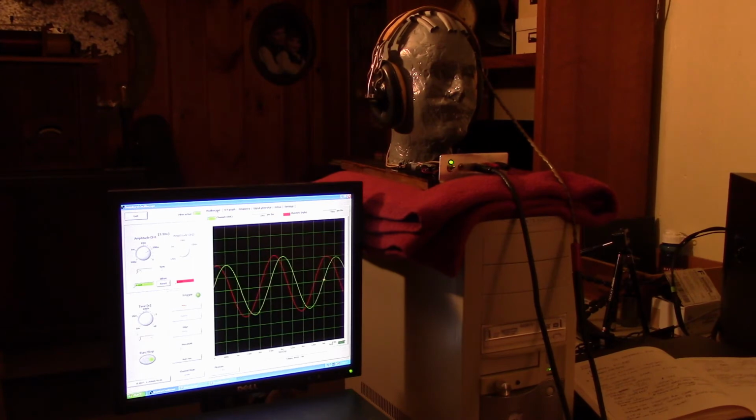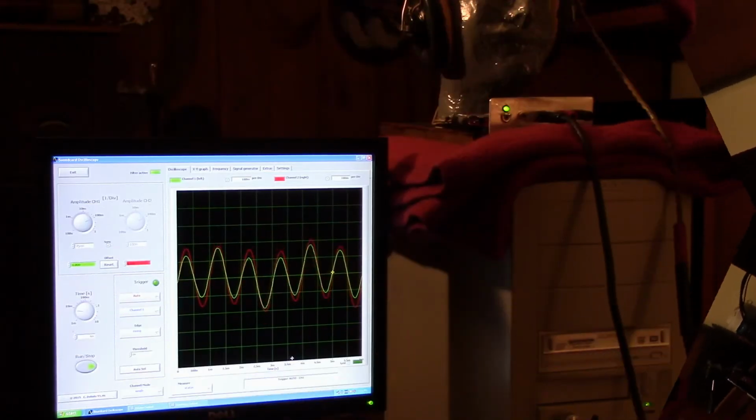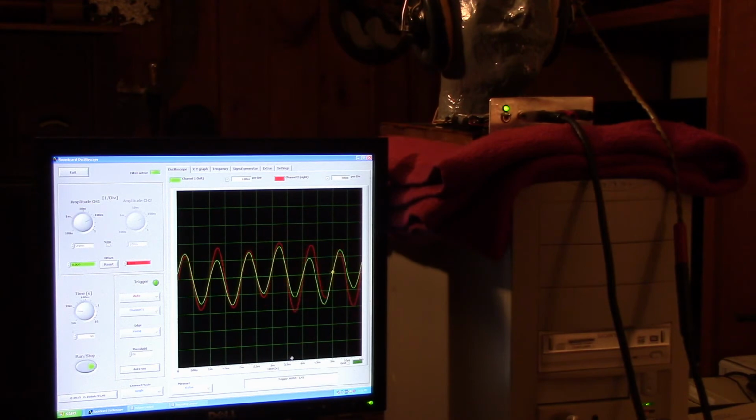Again, military communications fidelity. So the military headsets, you can see as I'm talking, I'm bringing up the bottom, but military headsets pretty flat, and it has a peak, it looks like around 2.7 kilohertz, and then it begins to fall off. So I'm repeating the test we were doing on phase and amplitude at 1 kilohertz. As you can see, the HS33 A and B1 receivers are pretty much in phase at 1 kilohertz, so that lagging that we were seeing seems to have cleaned up at 1 kilohertz. So the headset is wired correctly from the factory.